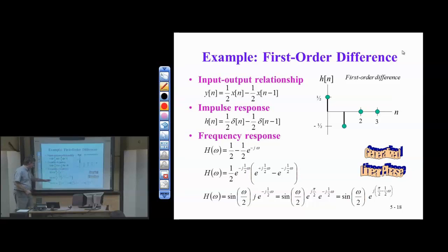Now, what's different is I get e to the j omega over 2 minus e to the minus j omega over 2. This collapses down to 2 times j times sine, and then the 1/2 knocks out the 2. So it's j times sine times what's remaining, which is nice because that's just again a delay by 1/2 sample. Now the j is something, so I can write this in complex form: that j is e to the j times pi over 2.